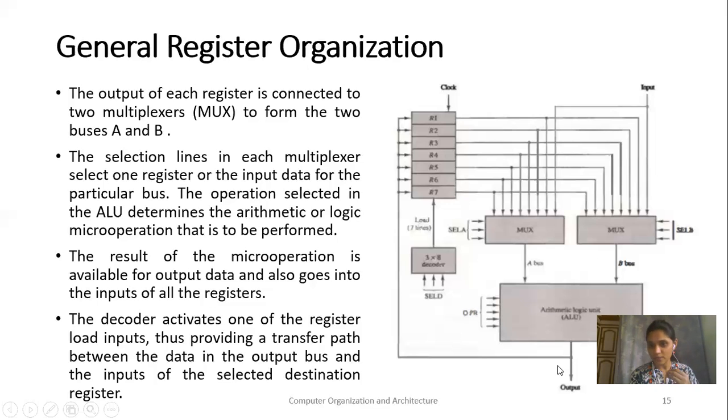The output is generated here, and that is going to be stored into register R1, so for that we have to provide a selection to store this content into register R1. Our main task is selecting the input for mux A, mux B, the operation of the ALU, and the selection for the 3 to 8 decoder, select D.